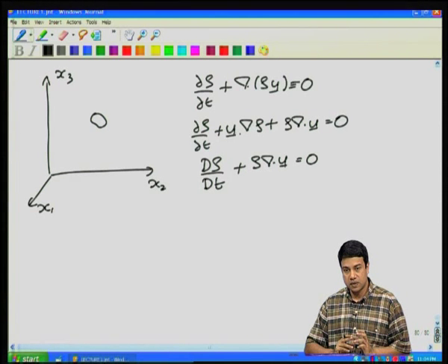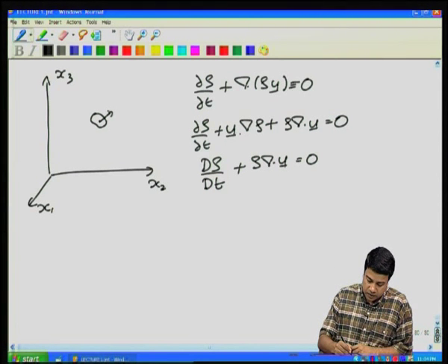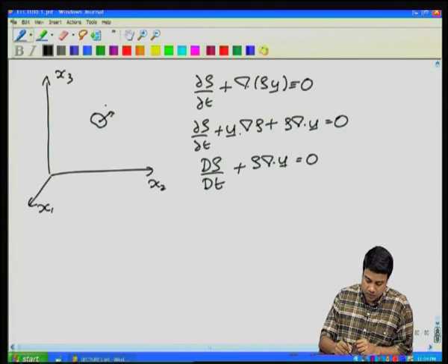It is rho at x1 plus u1 delta t, x2 plus u2 delta t, x3 plus u3 delta t, t plus delta t, minus rho at x1, x2, x3, t, divided by delta t. So, it's in a reference frame that is moving with the same mean velocity as the fluid. So, the difference in the density is at two locations which are separated by u delta t.